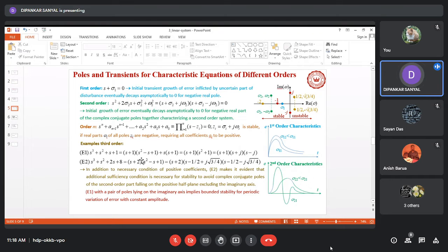So if the equation is of this nature, then we have a root here corresponding to this plus 2, and corresponding to this we have two roots on the positive side of the real axis. When we have roots of this form, clearly because of the positive nature of the real part, the error will keep on increasing with time and it will indicate an unstable situation.